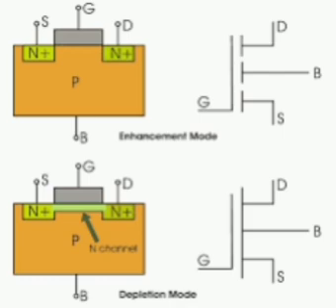VTN is positive and VTP is negative. For a MOSFET operating in saturation region, channel length modulation effect causes decrease in output resistance. In triode region, FET works as a voltage variable resistor. Transconductance GM equal to dou ID by dou VGS.